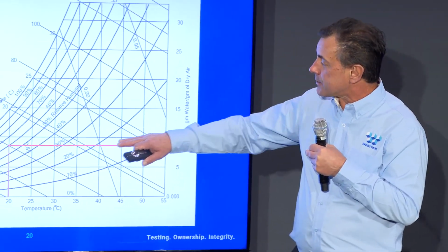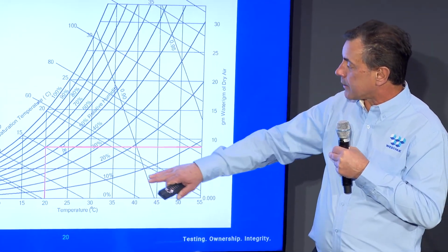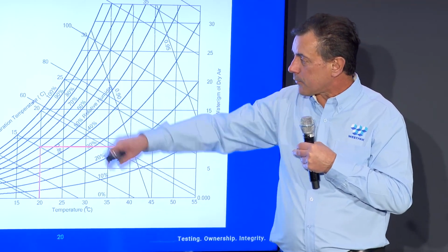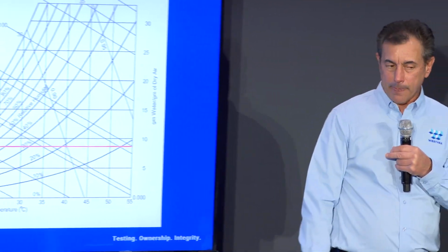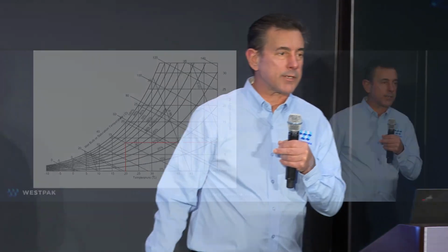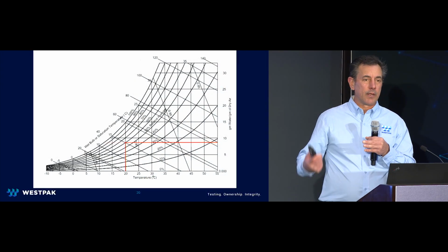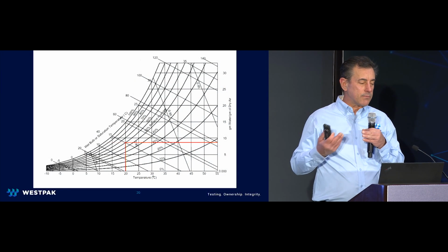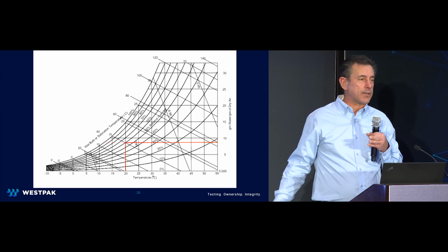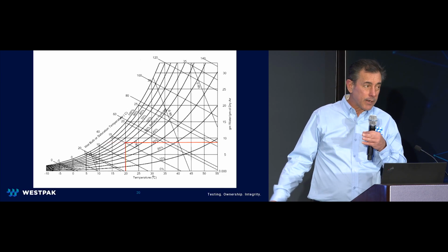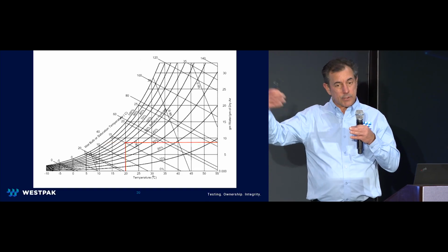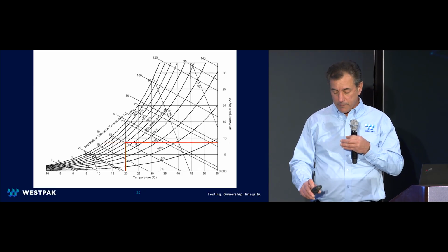And there's a whole lot going on, right? You see these curved lines? That's the relative humidity, 10, 20, 30, 40, 50, all the way to 100%. 100% is saturation. That's where the vapor pressure in the air has gotten so great that it just falls out. And that's where we get rain, right? If we have 100% saturation, that's when rain occurs.